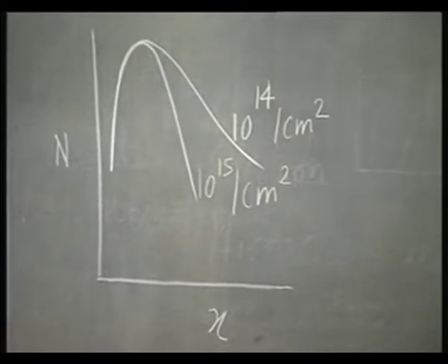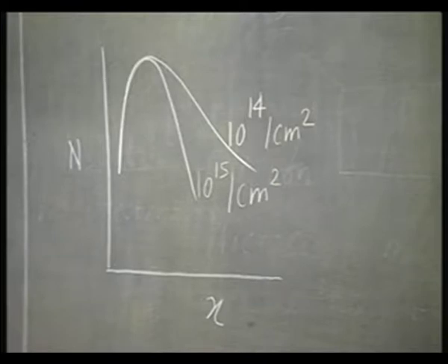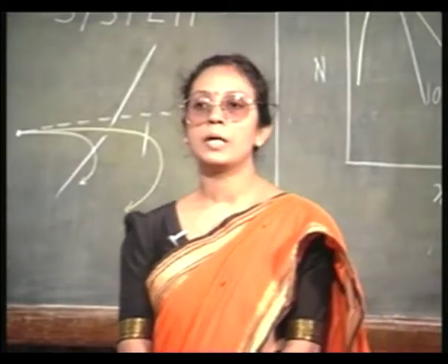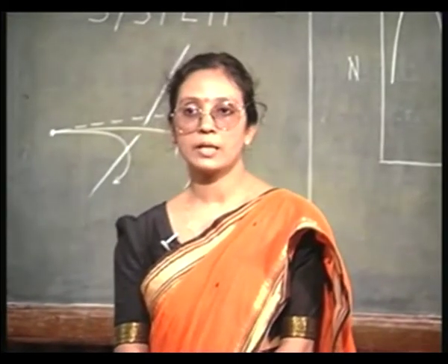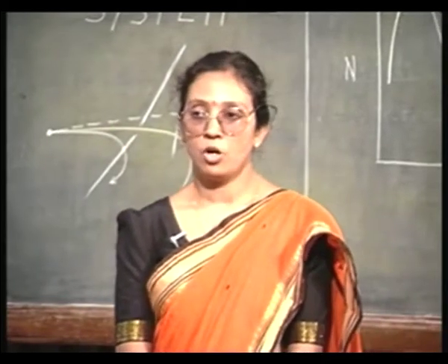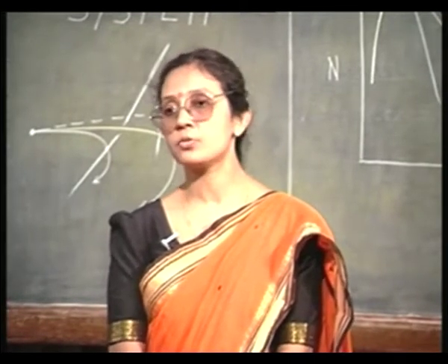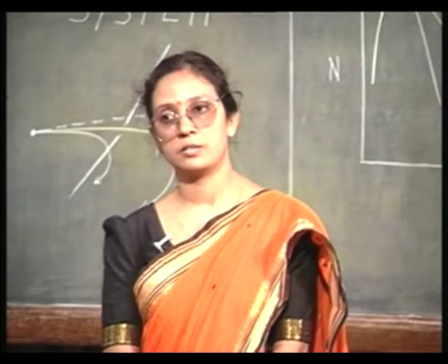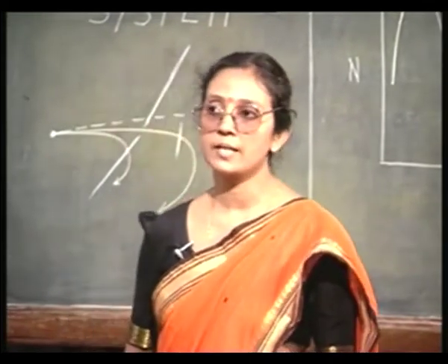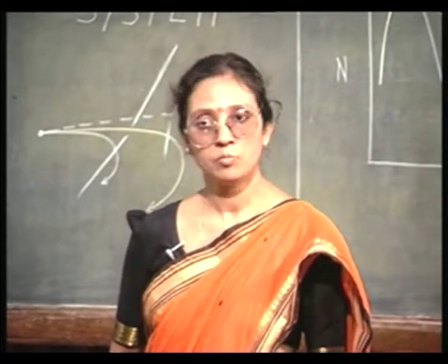That is why sometimes prior to implantation, silicon is pre-amorphized by self implantation or by an inert implantation. You can either implant argon or neon, or you can self implant, that is, you can implant silicon on silicon, in order simply to amorphize the region. So that in that amorphous region, when you next carry out the implantation, the profile will resemble a Gaussian more closely.